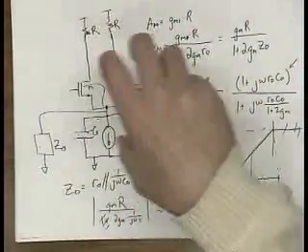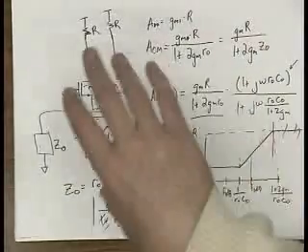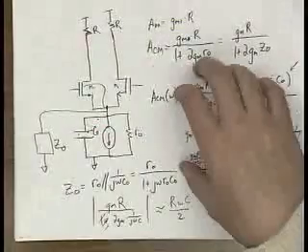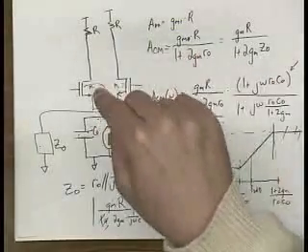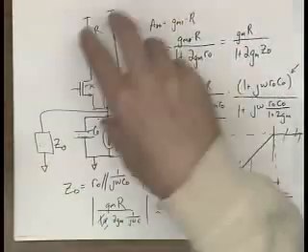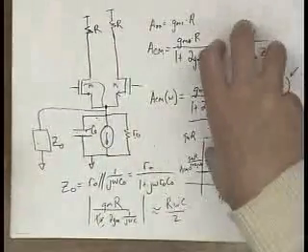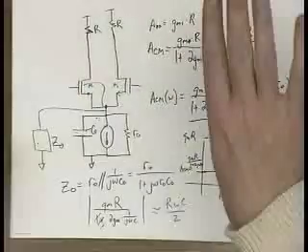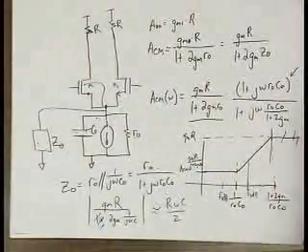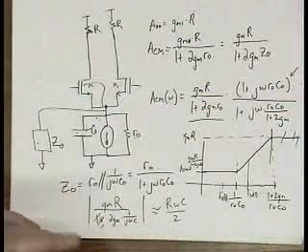Chances are, if you have multiple diff pairs, then the differential versus common mode gain of each of those subsequent diff pairs will be high enough that you almost certainly could do this. But if you only have one diff to single stage, and then you have one or more single stages, where you do the rest of the gain with single-ended in, single-ended out, then you may or may not be able to make it.